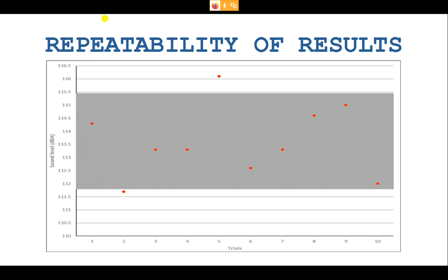So basically you have to try with different combinations and find what the Mach number or the amplitude is which we get, and then find the average of that particular series of data, find the standard deviation, and then find the percentage of variation. From this you can easily find the repeatability of your results, which will instill confidence in the results which you get from your own experiments.